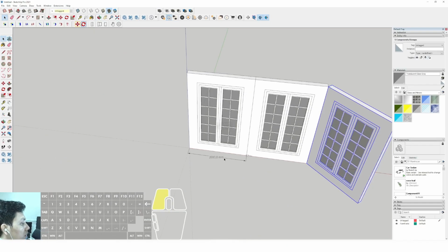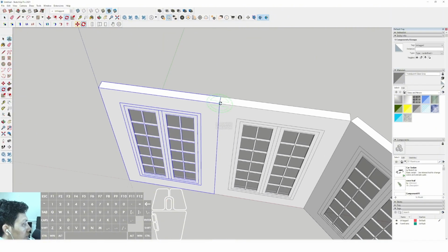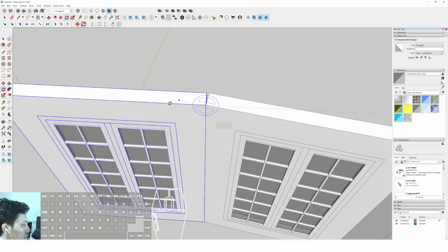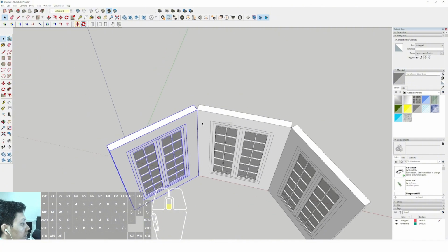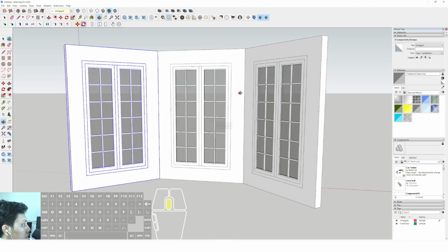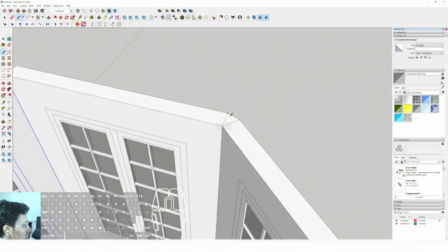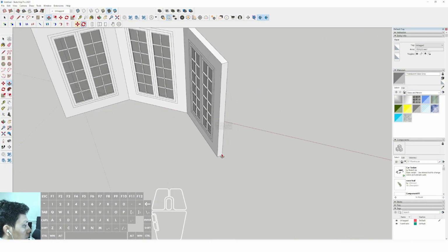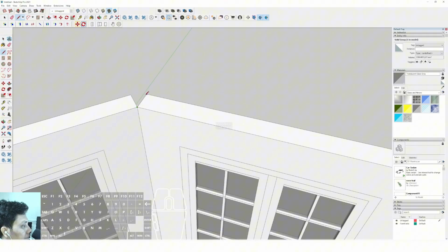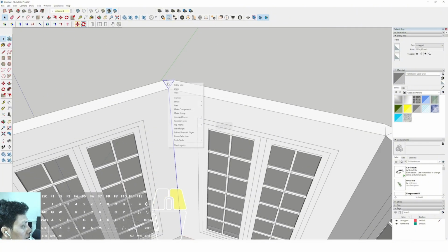and also this one. We can erase some unnecessary object first. Okay, then we can select Q, rotate 45 degree, and this is a bay window anyway. Okay, and we can complete this one with a line. Okay, we can complete with a line and make group, and also this one we can complete with a line in here and make group.